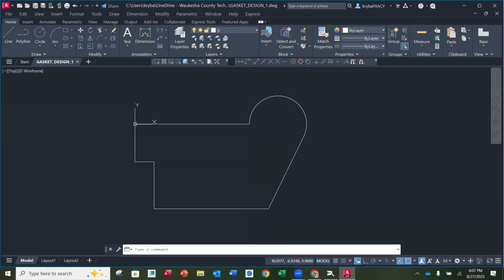So let's go back to AutoCAD. The fillet command is right below the trim. I'm going to click on the fillet command. And remember, the first thing I need to do, it's going to say start clicking on stuff, but I have to set the radius. The last radius that I used, I think, was 2, right? Okay, whatever we did on this session. So I'm going to hit R, enter. And then I don't want it to be 2. I want it to be 1, enter.